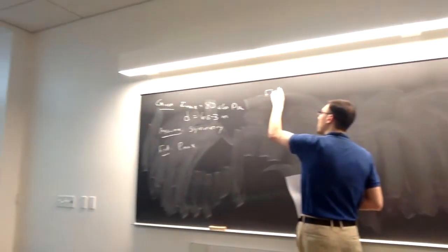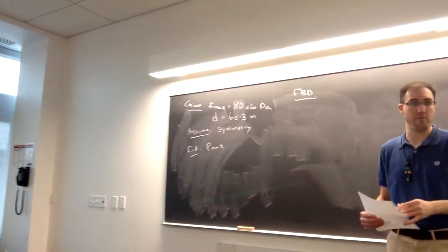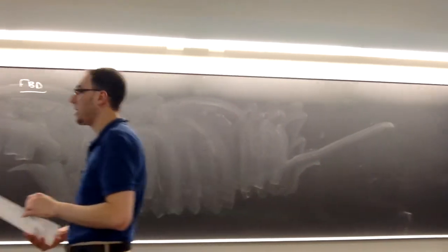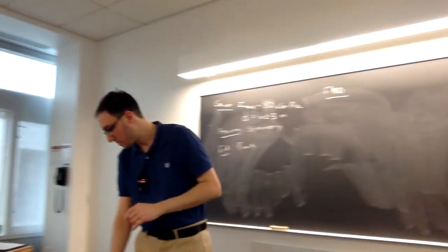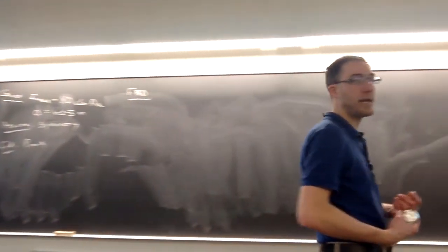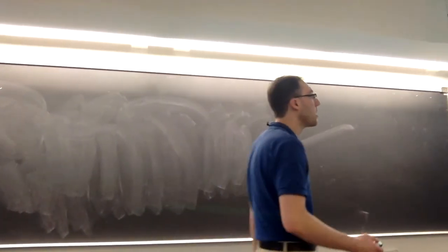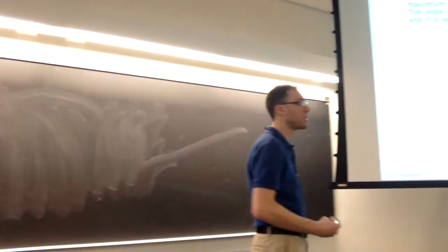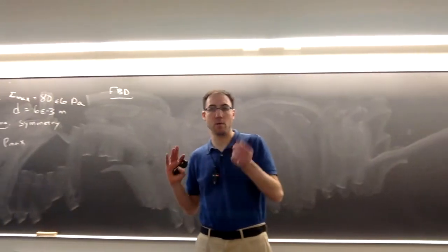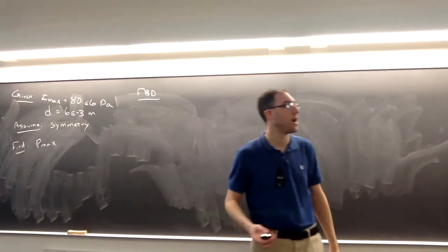In order to find shear stress, we need to know the internal shear force in our bolts. So we're going to need a free body diagram to do this. The free body diagrams now for internal loads are not necessarily as simple as we were seeing before. We have to see how we can cut through this so that it exposes the things we're interested in without including things that we're maybe not interested in or don't need to find.